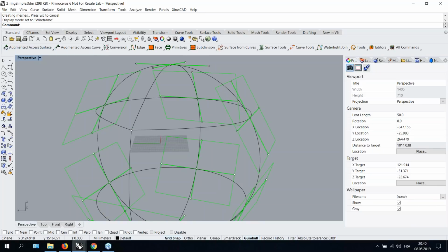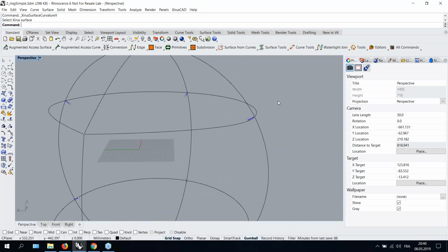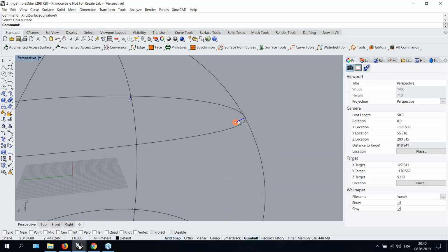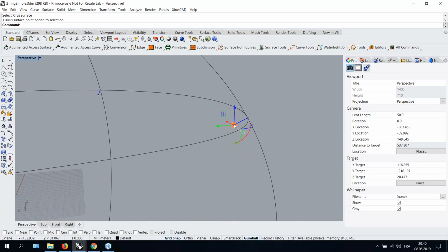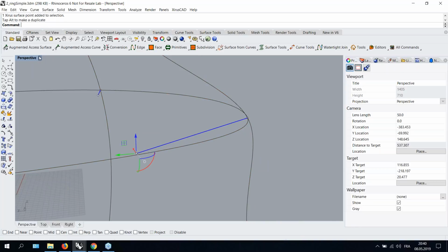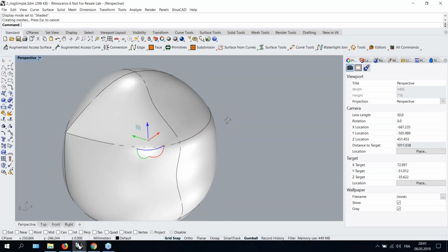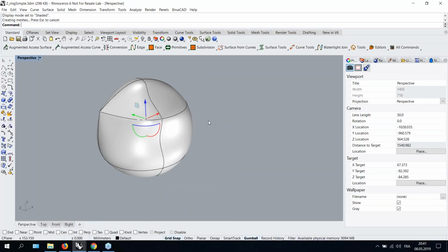This is much more for, let's say, advanced users who really like to have very particular curvature values. But this handle that you see here, the blue one, is actually in fact the curvature at this point. And as you can see, now I'm modifying the curvature of the surface without actually touching the tangent plane. So if you want only to modify curvature, you can even do that directly through the handles as well.